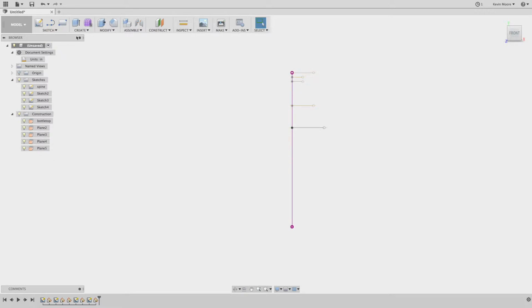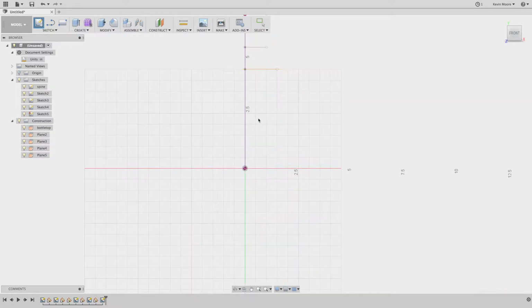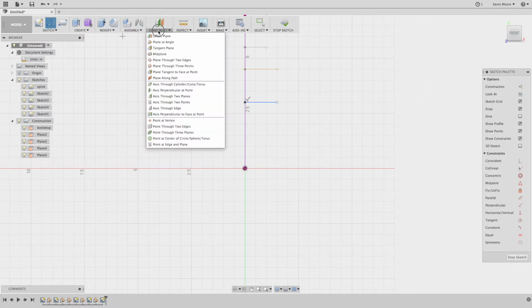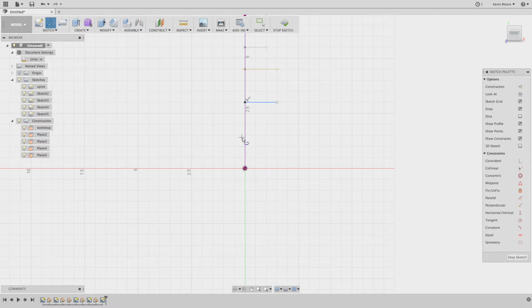And then we go sketch, create sketch, click to set the plane that I'm working on, L for line, and then I'm going to do maybe just 2 more for now. One right here, and then click on that to get out, construct, and you can do all of your lines first.